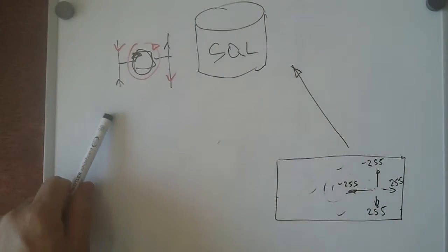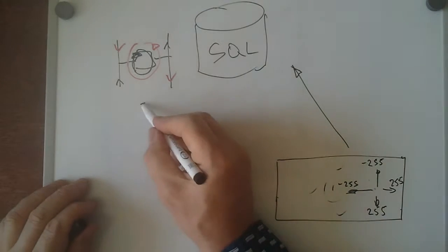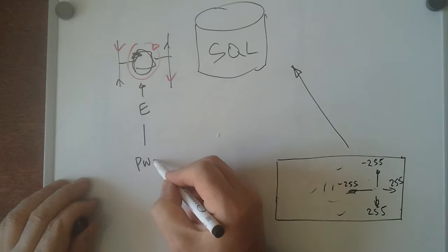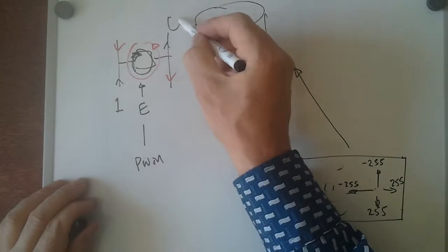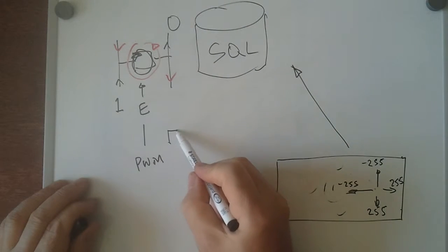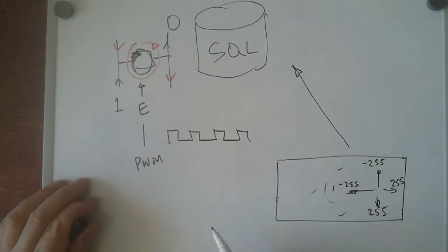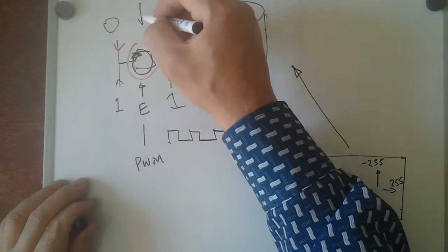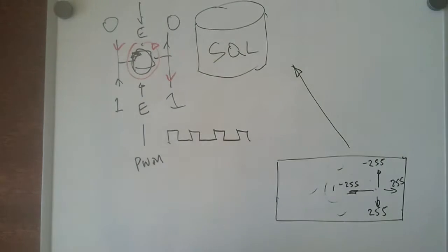So that's a motor controller, and then there's an enable pulse, which you can pulse width modulate. So if you want to go forward, you send this high, this low, and you pulse width modulate to show how hard you want the motor to work. And if you want to go the other way, then you set this high, this low, and again there's another pulse width modulation signal that comes in here, so you modulate it that way.